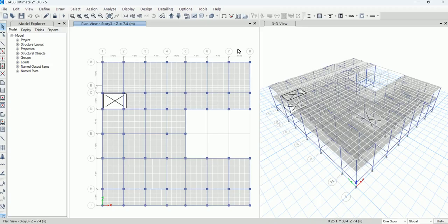It also depends on the purpose of the buildings. So we already calculated the loads depending on the finishing material, the unit weight of the finishing material, and we will apply the floor loads in area, kilonewton per area, or unit of force per unit area, depending on your system.